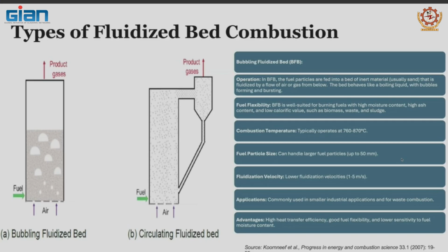Particle size, again, it could be different particle sizes. And you have to understand that in this environment, you don't really need to have perfectly round particles. By the attrition effect of the bed, if particles have sharp edges, they break off. They're filed off, and they become almost spherical.